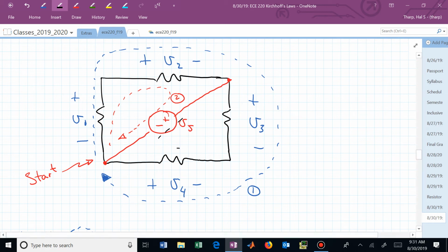Typically, when we're doing chapter 4, mesh analysis, you'll want all of your paths to be going in the same direction, clockwise, clockwise, clockwise. You probably don't want to be writing clockwise and counterclockwise. Then our strategy, sometimes you'll go, well, I thought it was always this current minus that current. Well, what have you done? Now you've got one path counterclockwise and one clockwise. You've messed up the whole beginning or foundation of how we write these equations.